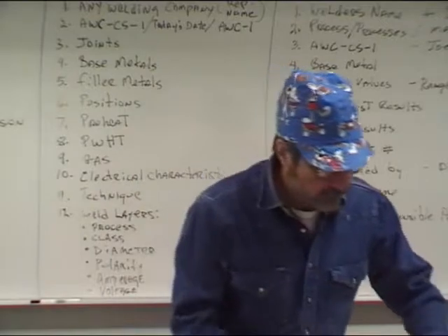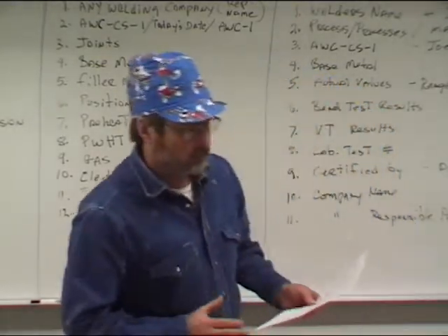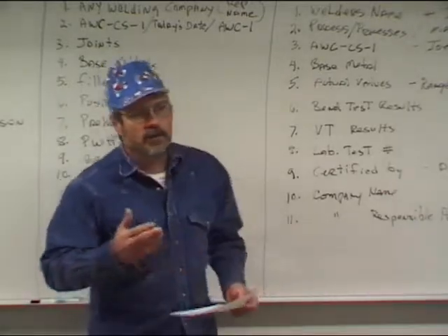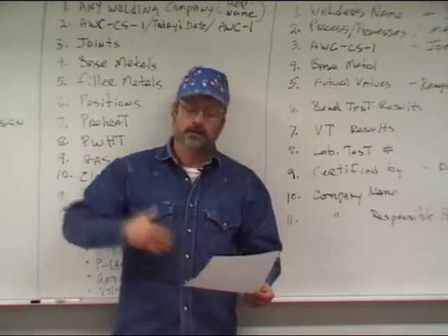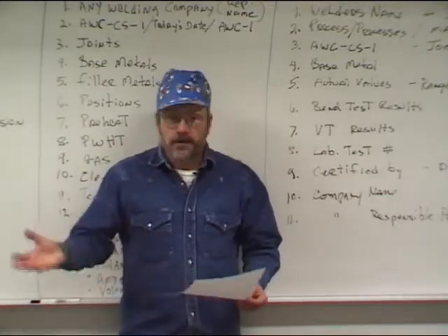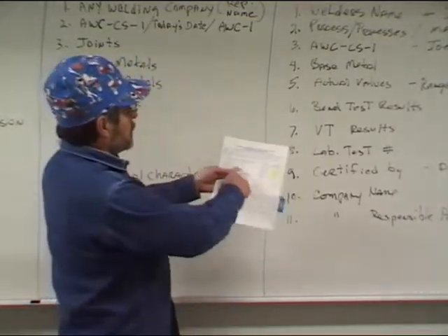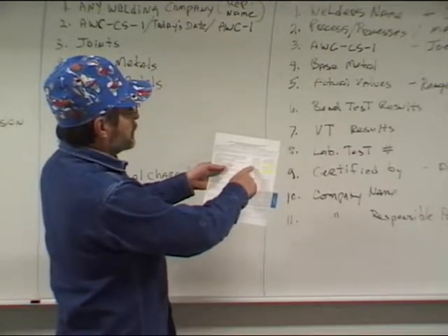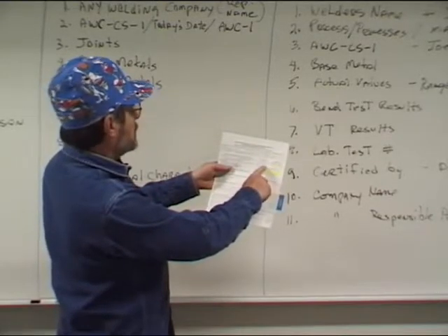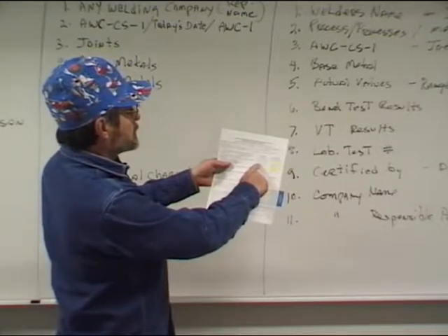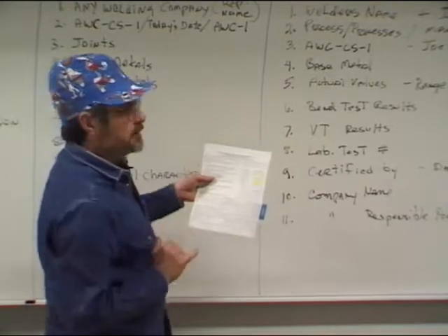But for the test that we just gave, if they took the test we've been describing, they would be limited to welding stuff that's just slightly below 3 inches to unlimited. So that's the range qualified. So that has to go in there. Then filler metal specification number 5.1 and 5.1, and then you're going to put the class E6010 and E7018. You're dropping down to the next line. It says F numbers. Well, we used F3 and F4, and now this puts some limits on them.